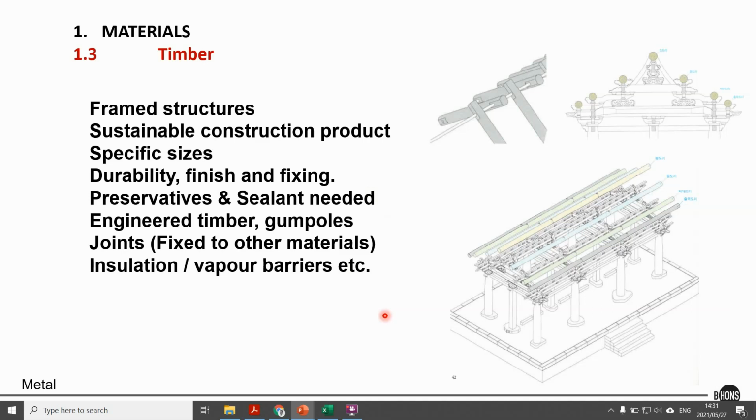Most timber joints, though, are mechanically fixed, but you can go and have a look at the work. There's a beautiful project by Kengo Kuma, The Nest We Grow, where they explore ways of fixing the joints of timber, not using mechanical or steel joints. And I think that's actually quite exciting. But it's certainly way more expensive. So you can go for simple mechanical fixings, and there you'll use steel that just shouldn't rust if it's wet conditions and so forth. But it's quite simple in the process, and quite easy to use.